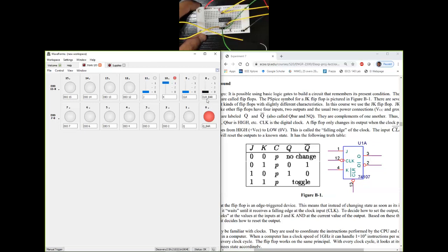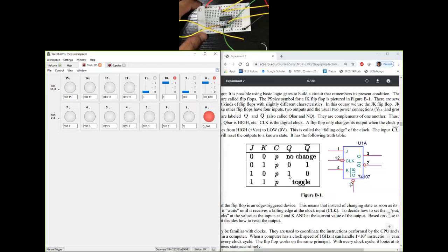So we have actually made clear bar 0, which means I'm always clearing this flip-flop. I don't want that. I actually want this as a start state. That is fine, I can start there. However, I cannot leave it there anymore. So I actually have to make this into a 1 there, so that now I am not clearing the flip-flop.